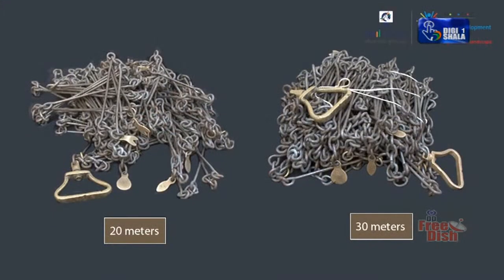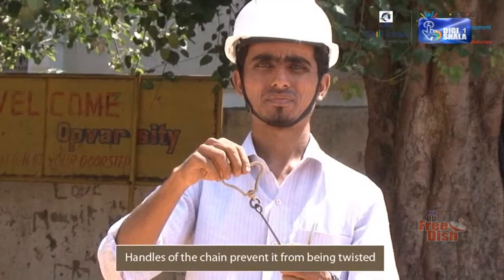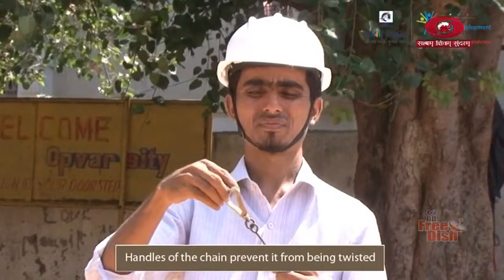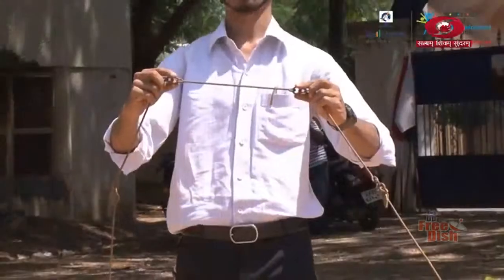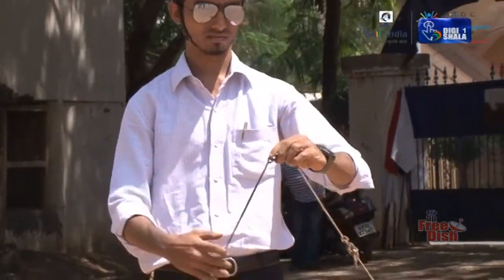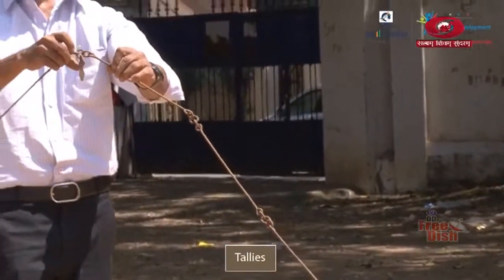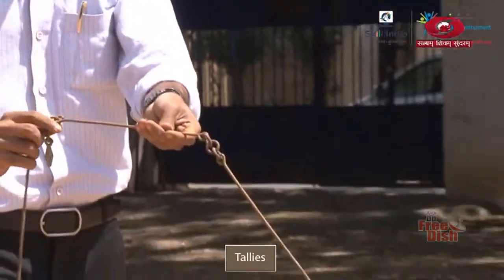The chains used in surveying have a fixed length, such as 20 meters or 30 meters. They are all made up of interlinked elements with handles positioned to prevent twisting of the chain. Metal pieces called tallies mark equal divisions of length on the chain. They help in knowing intermediate measurements.